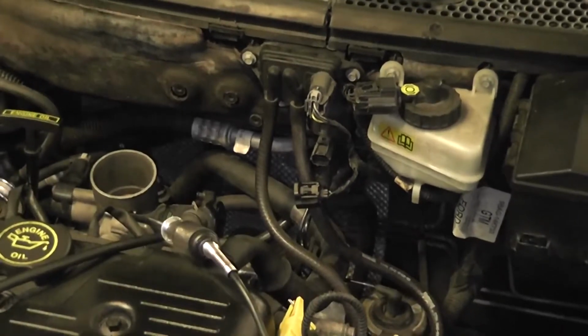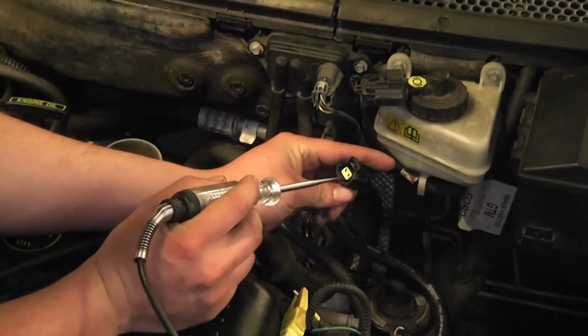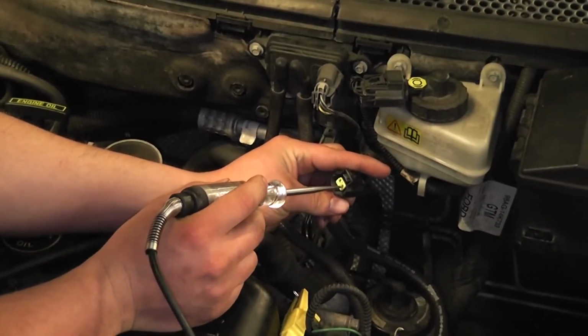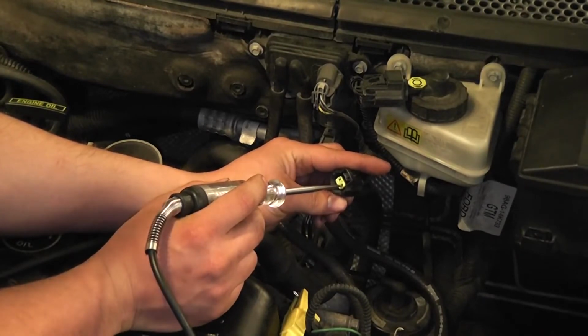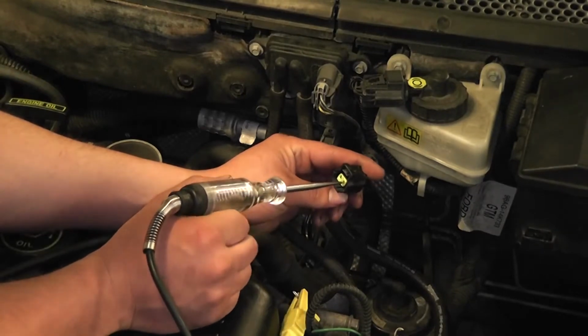And you want to hold that on there. One of the important things here is to make sure that you do not stuff this test light into this female pin. That test light is a much bigger diameter. If you were to do that, it would never contact the solenoid properly anymore. So we're just touching it on there. Can you move your index finger so I can see the, there you go, perfect.